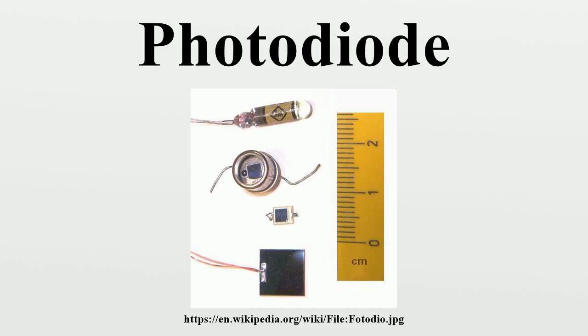Comparison with photomultipliers. Advantages compared to photomultipliers: excellent linearity of output current as a function of incident light, spectral response from 190 nanometers to 1100 nanometers, longer wavelengths with other semiconductor materials, low noise, ruggedized to mechanical stress, low cost, compact and lightweight, long lifetime, high quantum efficiency, typically 60 to 80%, no high voltage required.